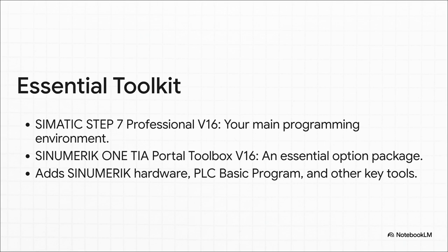That's your main workbench. But the real secret sauce here is the SINUMERIK 1 TIA Portal Toolbox. And I really want to stress this. This is not optional. It's the magic ingredient that adds all the SINUMERIK hardware into your catalog, gives you the basic program libraries and tools like the NCVAR selector. Honestly, without it, you're just looking at a generic programming environment, and that's not going to work.